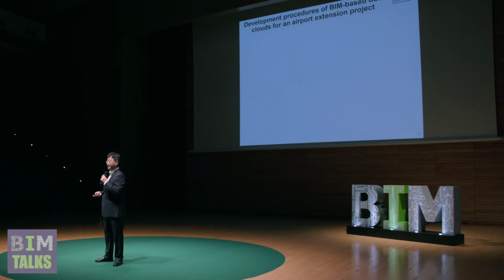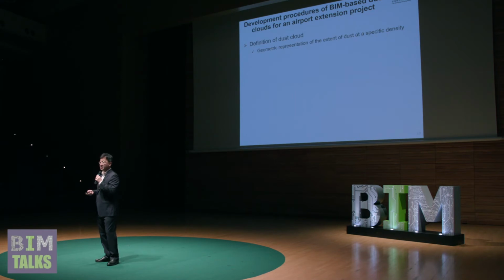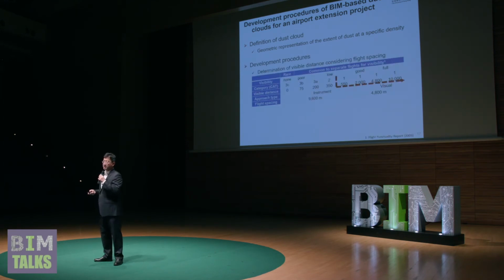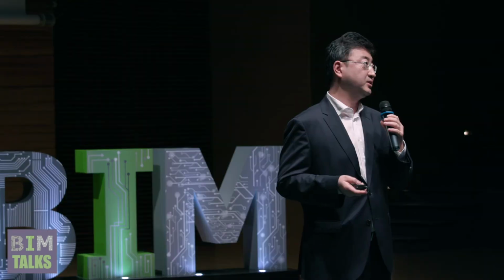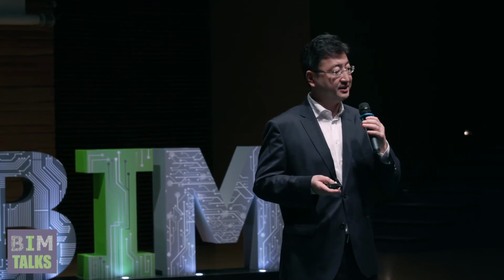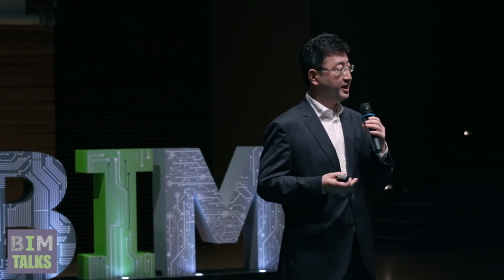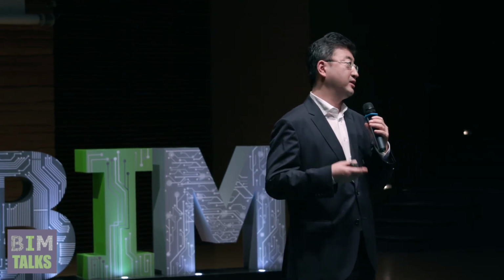So we first defined a dust cloud as a geometric representation of the extent of dust at a specific density. Then we determined a feasible distance considering flight spacing, carried out atmospheric dispersion modeling, and identified the extents of dust at specific densities. Finally, we generated a 3D solid to represent the dust cloud, considering different weather conditions.